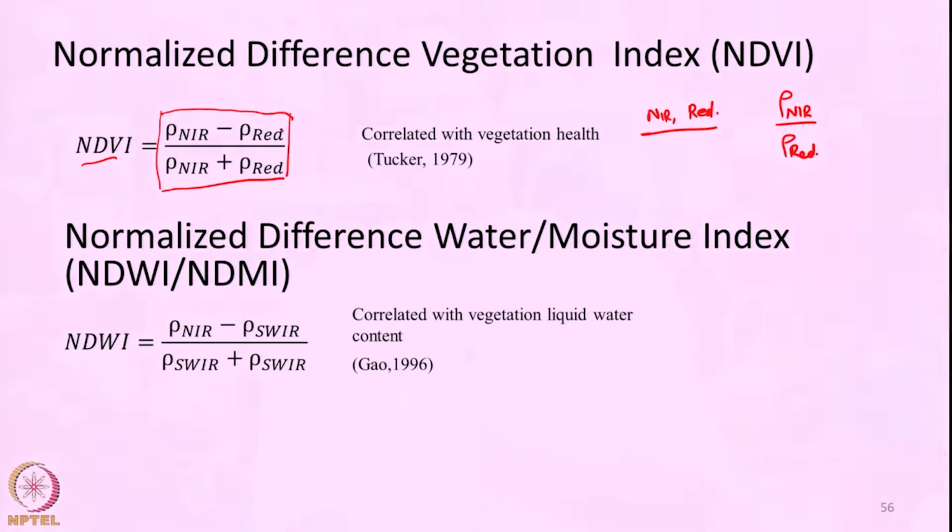So, what does it help with? Let us look at the name, normalized difference vegetation index. It is a vegetation index primarily developed to monitor vegetation, that we can understand. Difference, we are taking a difference of spectral reflectance in two bands, NIR and red. So, that is why it is called difference. Then normalized, here normalized means we are changing the reflectance values and bringing them to one single range, that is, the physical range of NDVI will vary from -1 to +1. It is now bounded on both sides. On the lower end it is -1, on the upper end it is +1.